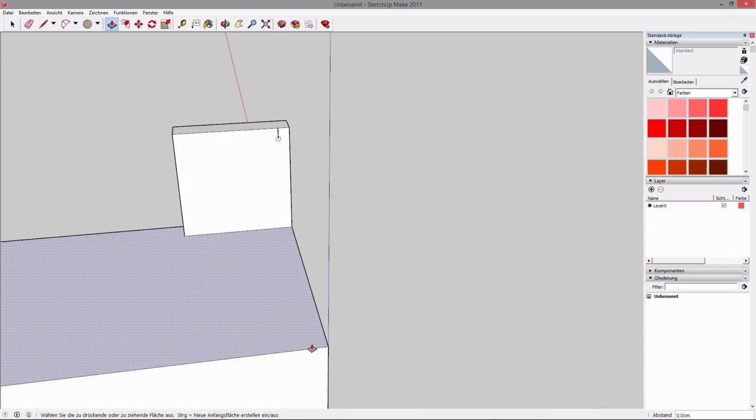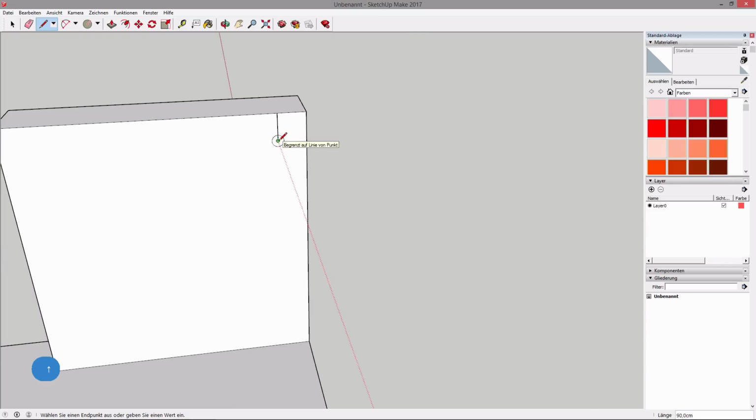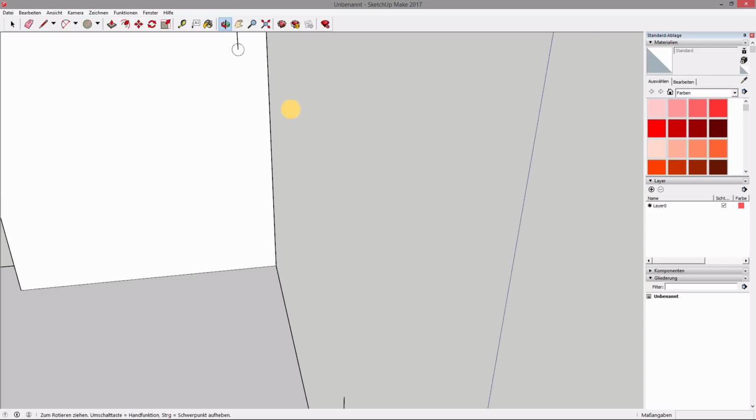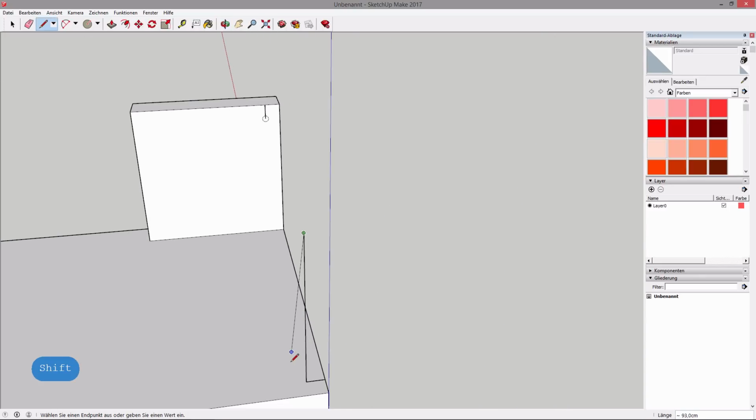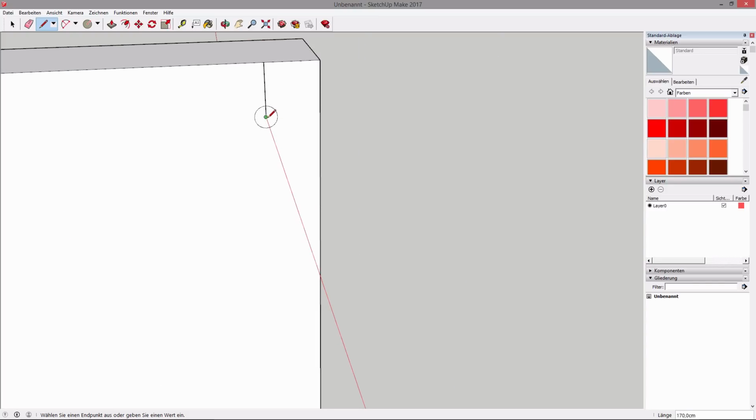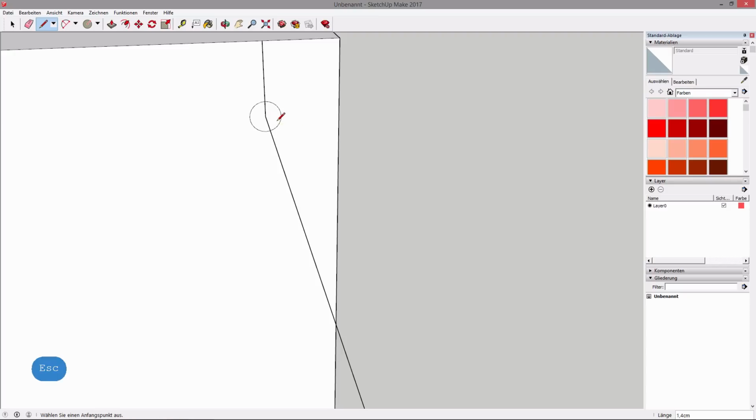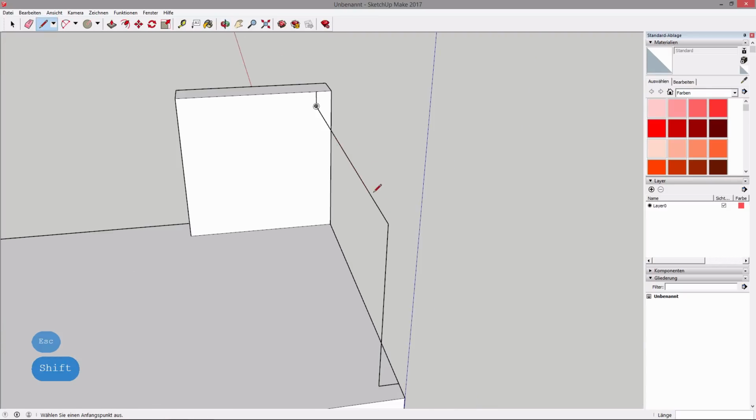So we use our line tool, click on the corner down there, go in 10 and 10, same distance. So I show you a workaround which is much easier to work in the right direction. You start drawing the line, click your arrow up, and then you can just point in the center of the existing circle and drag a line into the center. We see it's red, so it's perfectly aligned to the red axis. And now we have an easy way to place our bars.